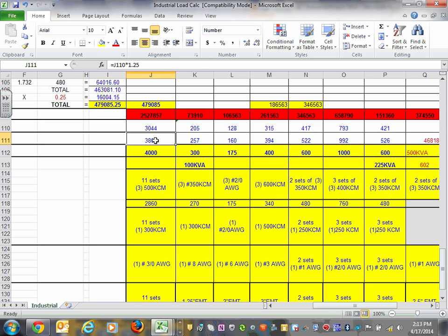You don't have to do that if you're not upping it, but it's a good idea, guys, to think about it. Sometimes if you want to expand 25%, you don't even have room to expand. But if you put 0 here, you can see we're expanding. We're assuming they're going to add circuits to all these panels in the future. All the panels, including the switchgear, have 25% capacity for future use. You don't have to do that again. So you can see how all these numbers at the top, we multiply them by 1.25. So gentlemen, you end up with a switchgear of